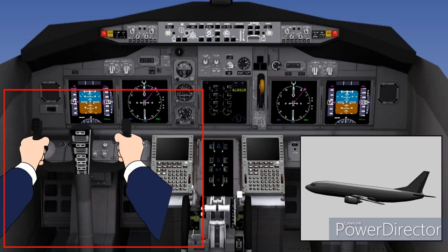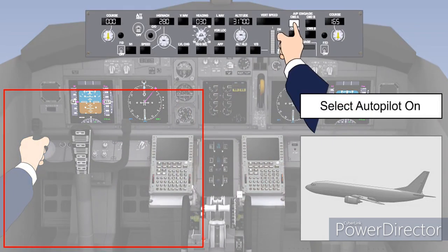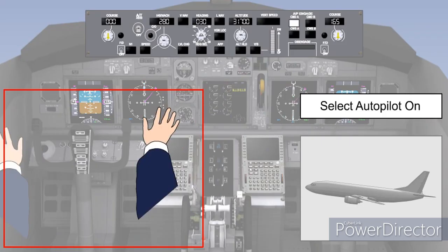Within the flight control computer, there are synchronizing circuits which will continually synchronize the autopilot with the attitude and trim of the aircraft, so that at the point of autopilot engagement, the autopilot will take control of the aircraft smoothly, without jerking or the tendency for the control stick to be snatched from the pilot's hand. The autopilot will then maintain the attitude that existed at the time of engagement until further guidance commands are selected by the pilot.